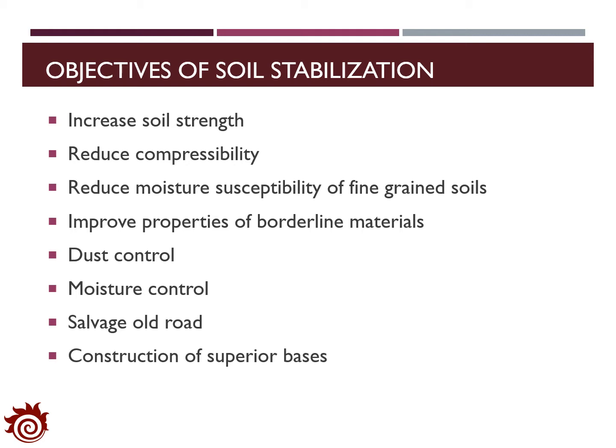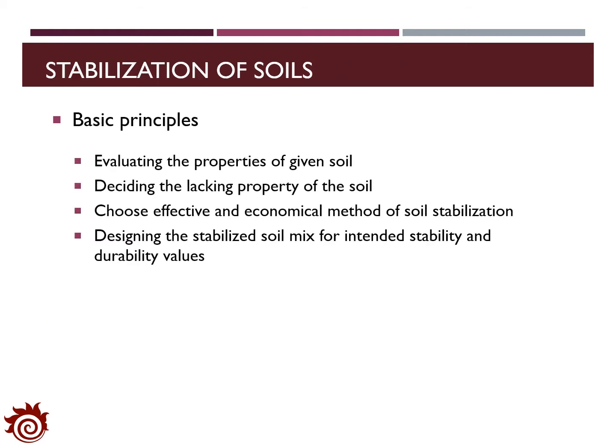In soil stabilization, there are some basic principles we need to follow. First, we have to evaluate the properties of the given soil, including the strength, stiffness, and the impact of the moisture contents. And then, with the requirements of the pavement, we need to decide the lacking properties of the soil to support the pavement structure.